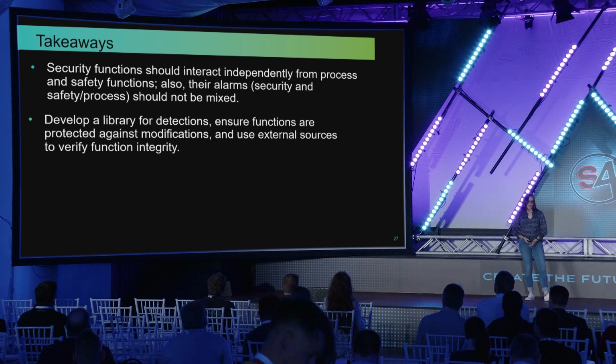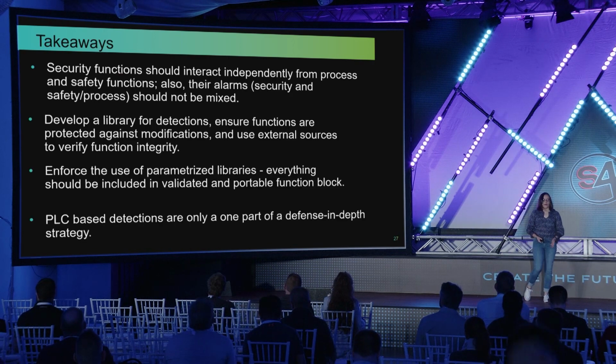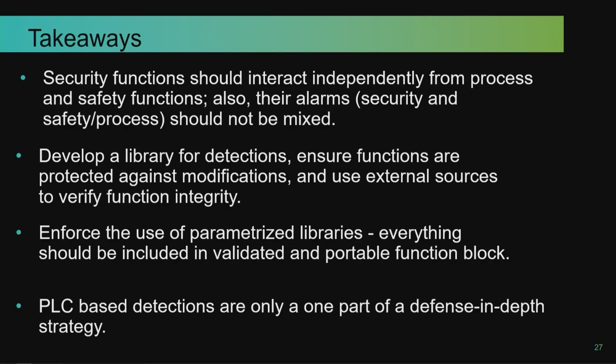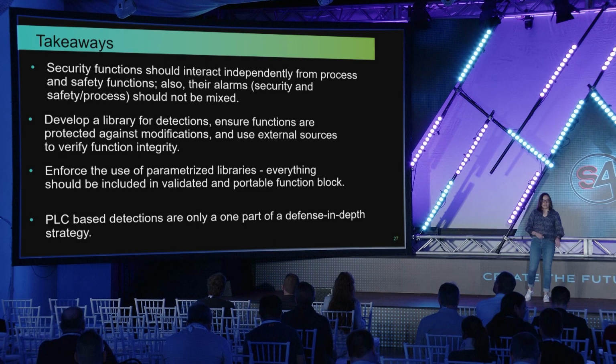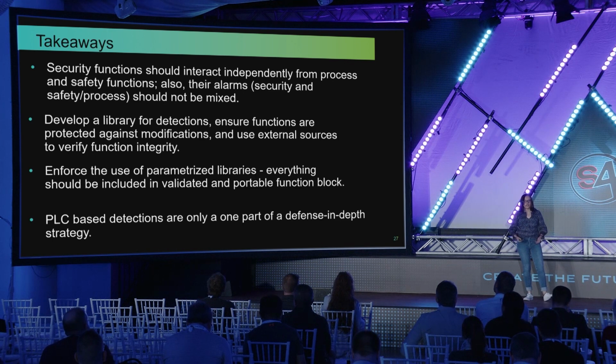The takeaways that we have are: create security functions, but don't mix them with operations. It is very important that you separate them, because it is also easier for the automation engineers to create them, to test them, and also to do the commissioning. And create libraries. It's very important that you always create libraries and just generate the parameterizations and use what you already have in the PLC. There are a lot of tools that you can already use.